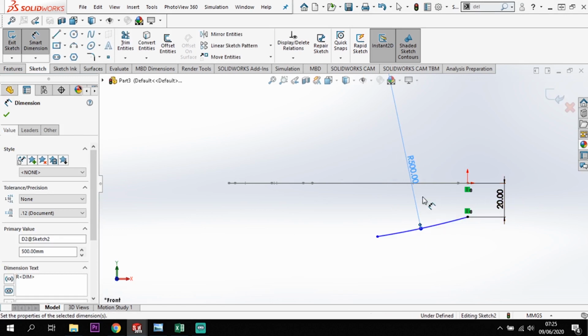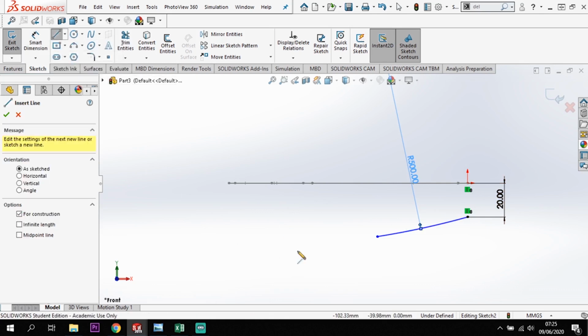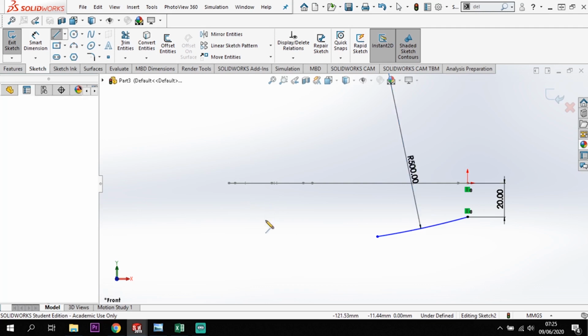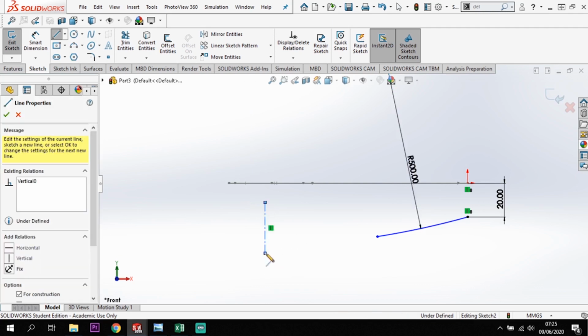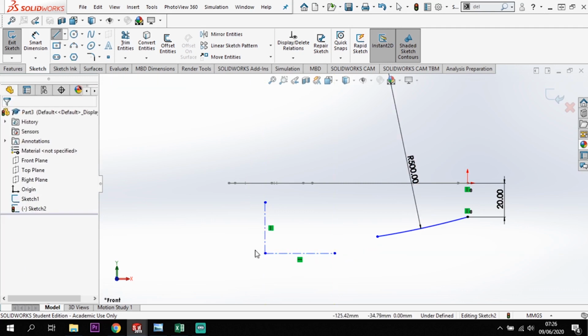Okay, now what I also want to do is to create some guide positions. I'm going to go to center line here, and I am going to put in 2 center lines there. Now these 2 center lines are going to be helping me select specific positions on my drawing. Now first of all, what I do want to make sure is that I know where these positions start.